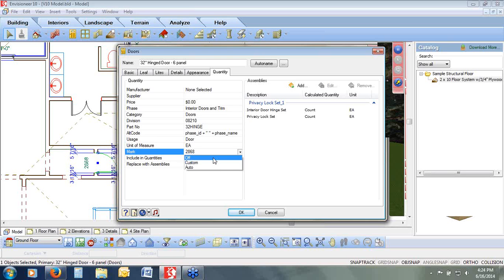So this will allow you, if you have removed a mark from a door, if it's set to off, then it won't reappear. So for those of you that are remodelers in the crowd, and I recognize a lot of the names in our attendee list here today, and I know some of you are remodelers, if you don't want to mark the existing doors, make sure they're set to off. They won't mark. Otherwise, they can automatically mark to whatever your settings and the program settings are, or you can do a custom one like I did here with 2868. So again, lots of flexibility there on how you're going to insert those door and window marks.